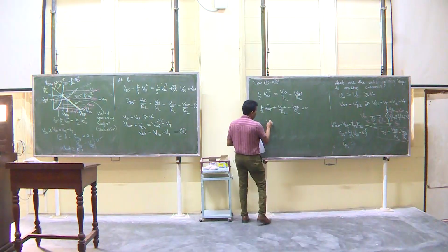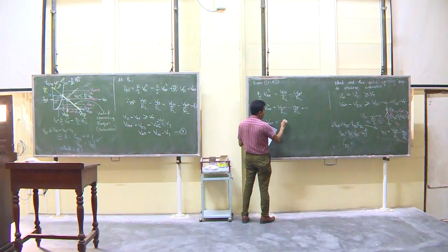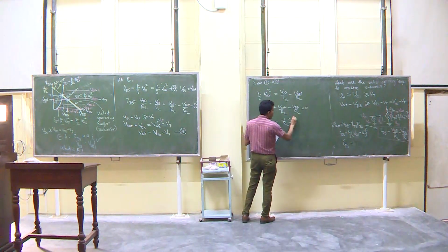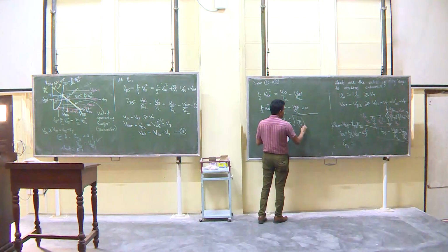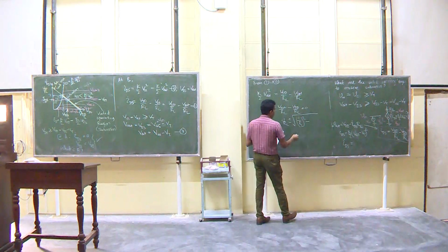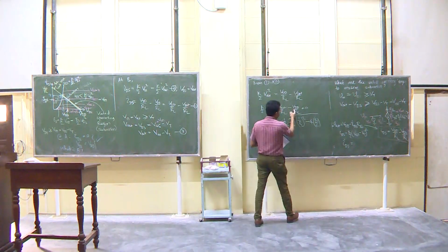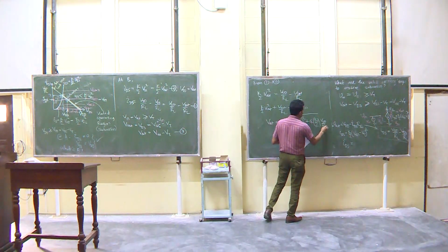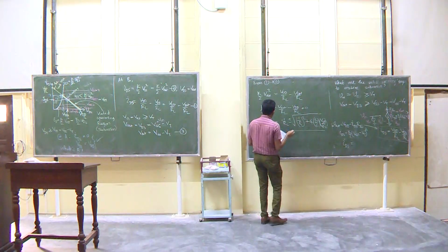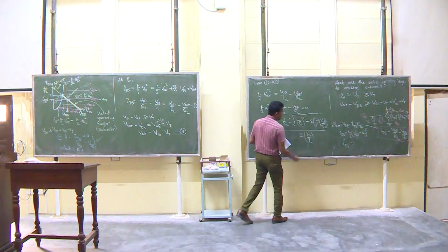So, therefore, V out is equal to minus B, which is minus 1 over RL, plus or minus square root of B squared, that is 1 over RL squared, minus 4 times A times C. C is negative, so this becomes VDD over RL, divided by 2A. Right?